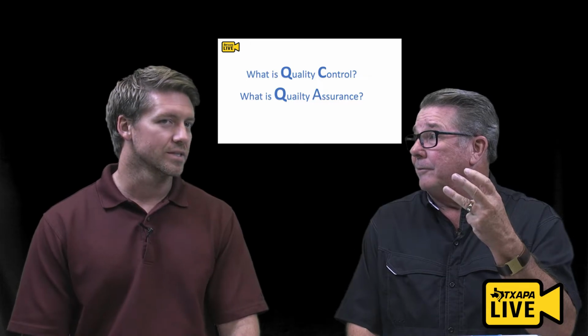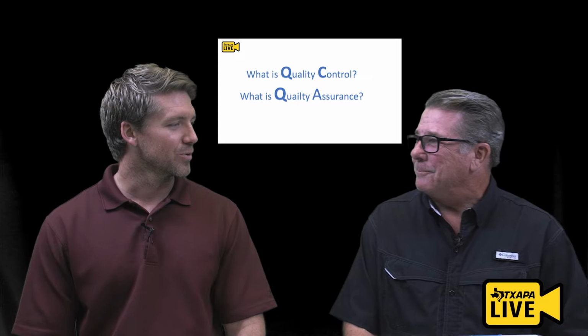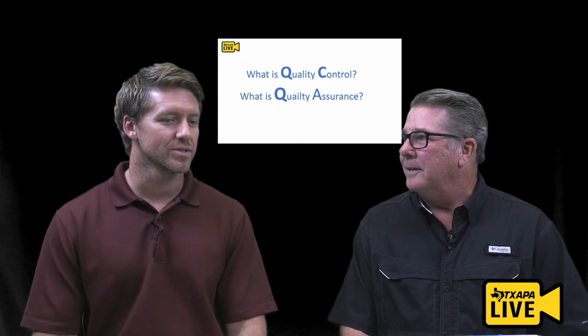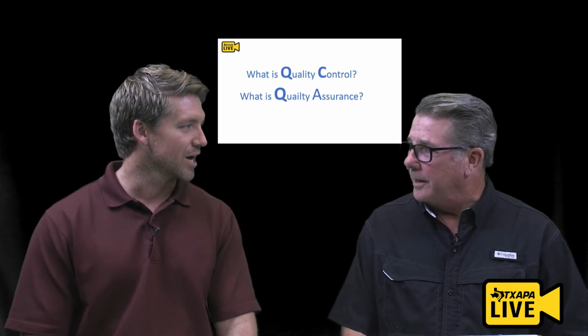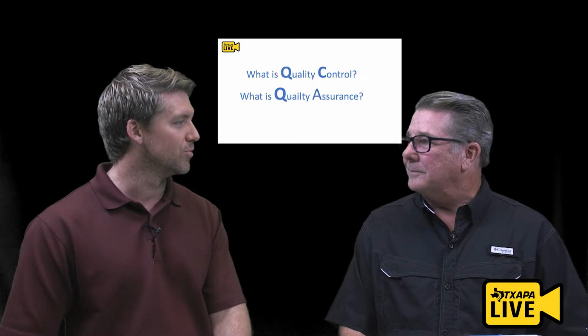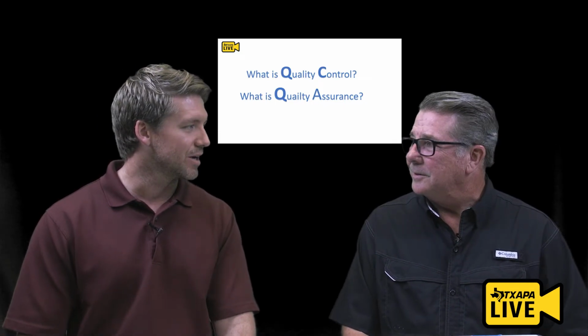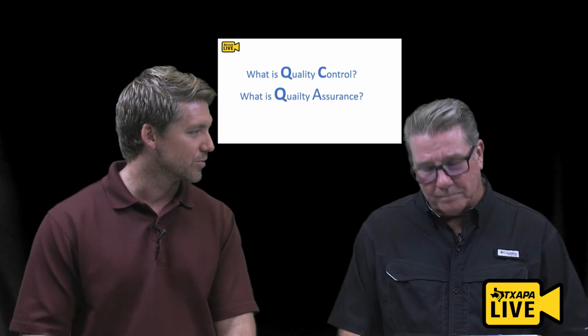Yeah, and the reason is that TxDOT, for quality assurance, is running them, right? That's right. So we're doing acceptance based on TxDOT results. So when TxDOT is not doing the testing per the guide schedule, right? If it's not required, then that responsibility is put off on the contractor to do more testing, and then TxDOT will have maybe minimal testing to verify at some given interval. Say 1 per 12 sublots, we'll do a test, and that just verifies that the contractor's results are in good line with what we're getting.